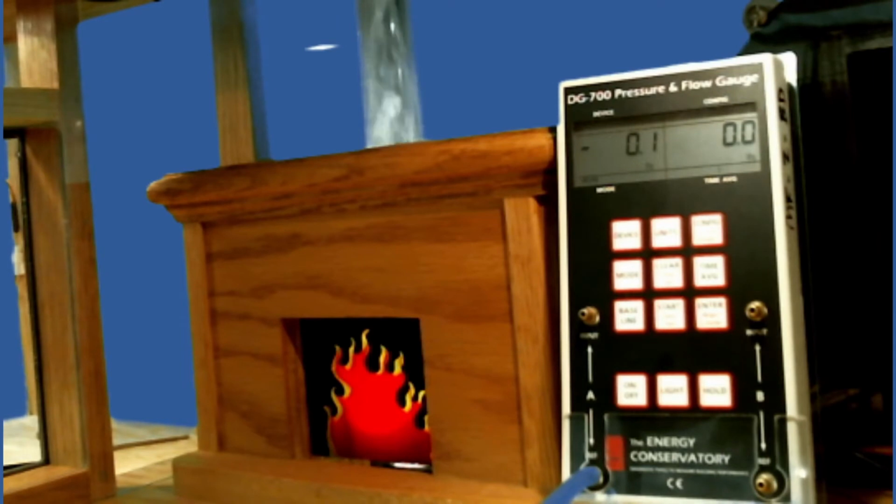So now you can see the manometer, and you can see the fireplace, and you can see which way the smoke's going. So you can see the pressure and the smoke. And I'm going to make a change in the house, and you should be able to know which side of the duct system I made a leak in. So I made a change, just a small change.